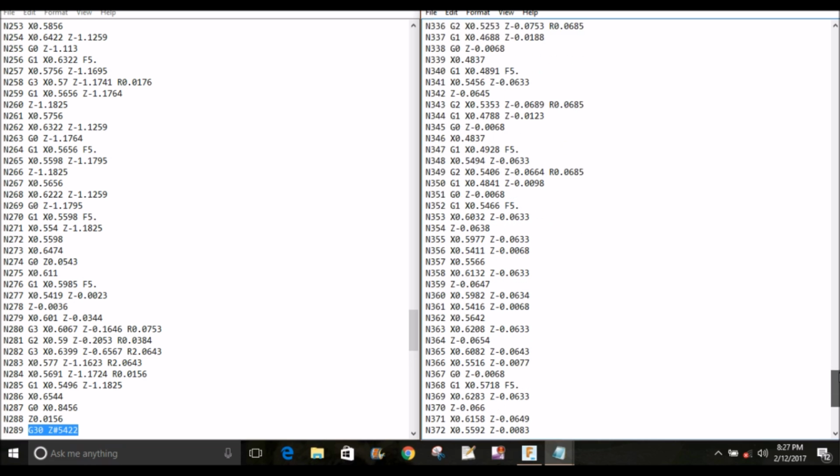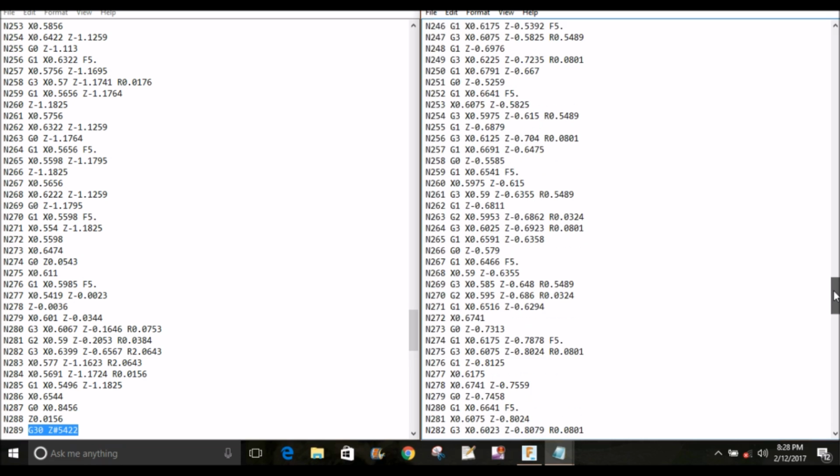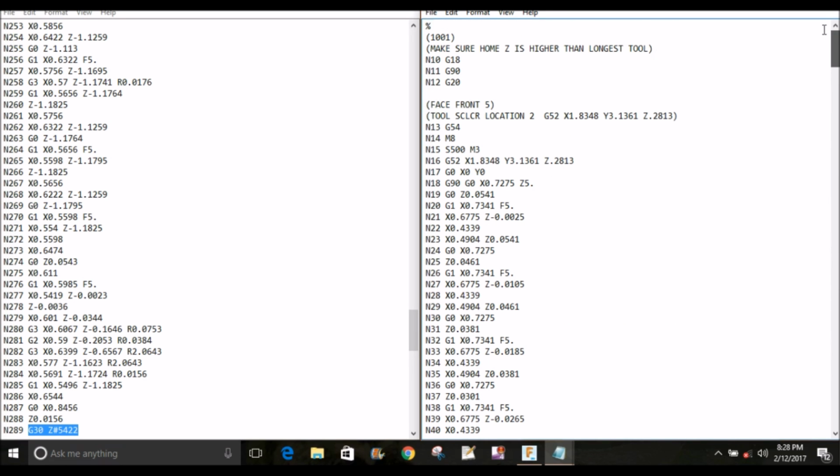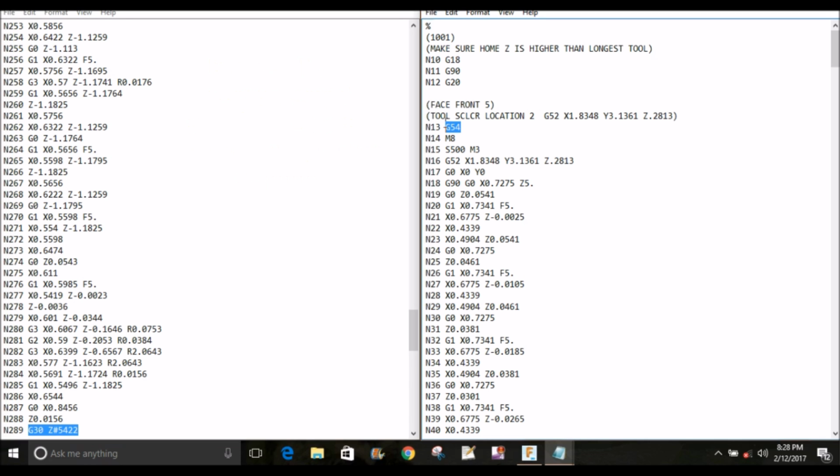And then that offset is canceled by this G52 here. And it goes down through, rewinds, and then when it starts at the top, it goes back to the G54. So that would be your origin, your zero on your tooling jig. That'd be the corner of my tooling block, and then from there it starts all over again. It'll go there.